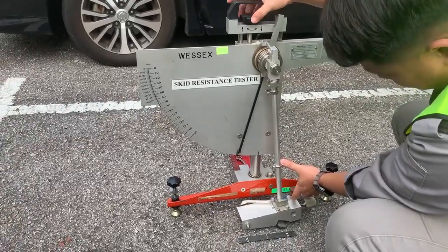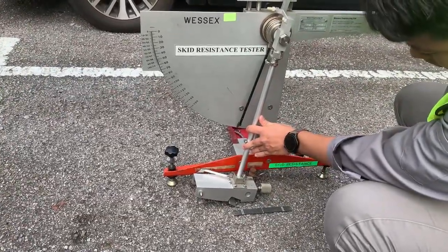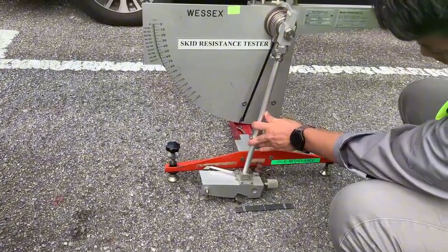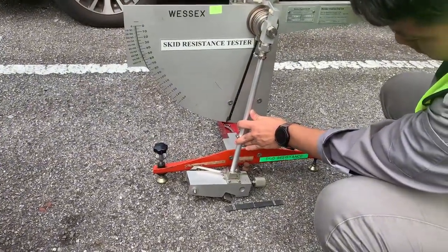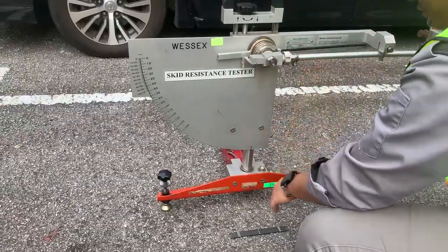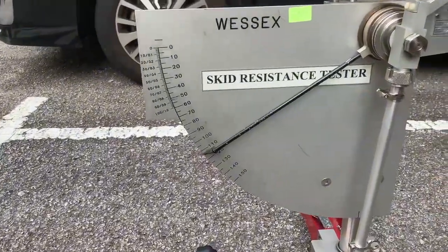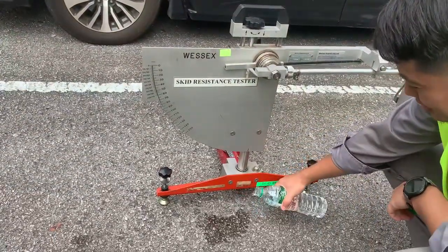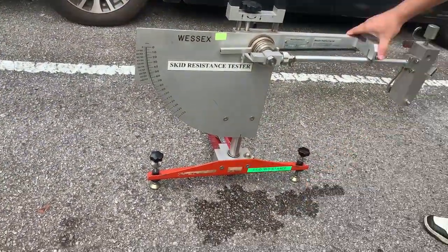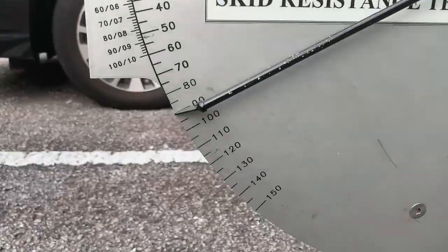Check the slide distance travelled by the slide rubber on the surface with the aid of a perspex ruler. Wet the test area. Make 3 swings and record the results. Make 3 more swings at the wetted test area and record the results. Then the steps were repeated for the medium rough surface and smooth surface.